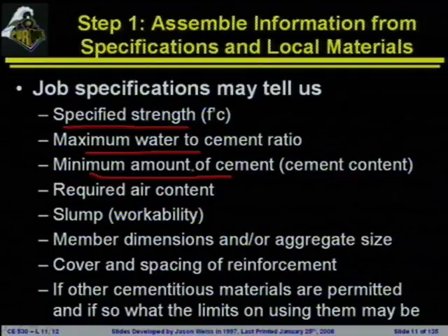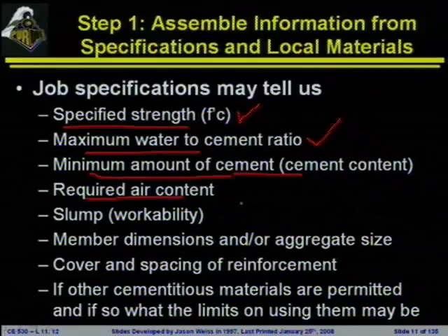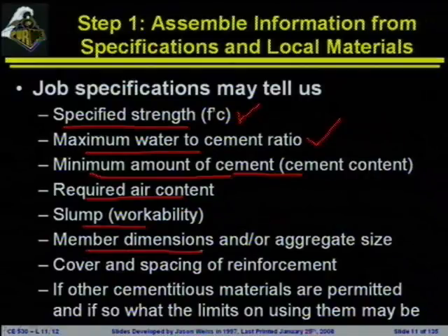So, for example, if you pull up INDOT's specifications on how to make a concrete, they will tell you the minimum strength, they will tell you the maximum water to cement ratio, and they will also specify how much cement that you need to use to get there. They will tell you the volume of air that you typically have to have if it's an exposed condition, tell you the slump that they're shooting for. They'll give you information on member dimensions or aggregate size and things on reinforcing steel.